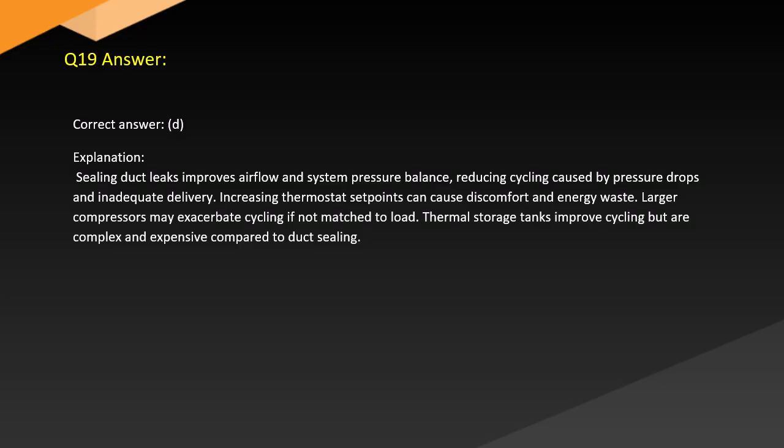Answer. Correct answer: D. Explanation. Sealing duct leaks improves airflow and system pressure balance, reducing cycling caused by pressure drops and inadequate delivery. Increasing thermostat set points can cause discomfort and energy waste. Larger compressors may exacerbate cycling if not matched to load. Thermal storage tanks improve cycling but are complex and expensive compared to duct sealing.